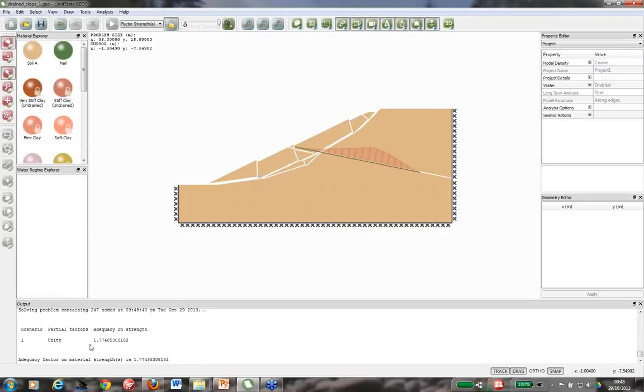We've increased the slope stability factor and strength to 1.77. The slope is able to slide, as it were, past the nail, but the nail is imparting tensile forces into that soil, which is being transmitted back through the nail, and this graph actually shows the axial or tensile force in the nail being transmitted back to its endpoint. So that is actually reinforcing it, and if we put more of these in, we would get more reinforcement.